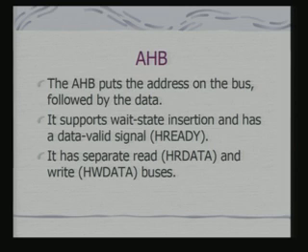So, how does it work? AHB puts the address on the bus followed by the data. If it is a write, the master provides the data. It supports wait state insertion and uses a data valid signal called HREADY, which is just like a ready or a wait signal that you find with ARM. It has separate read data and write data buses.